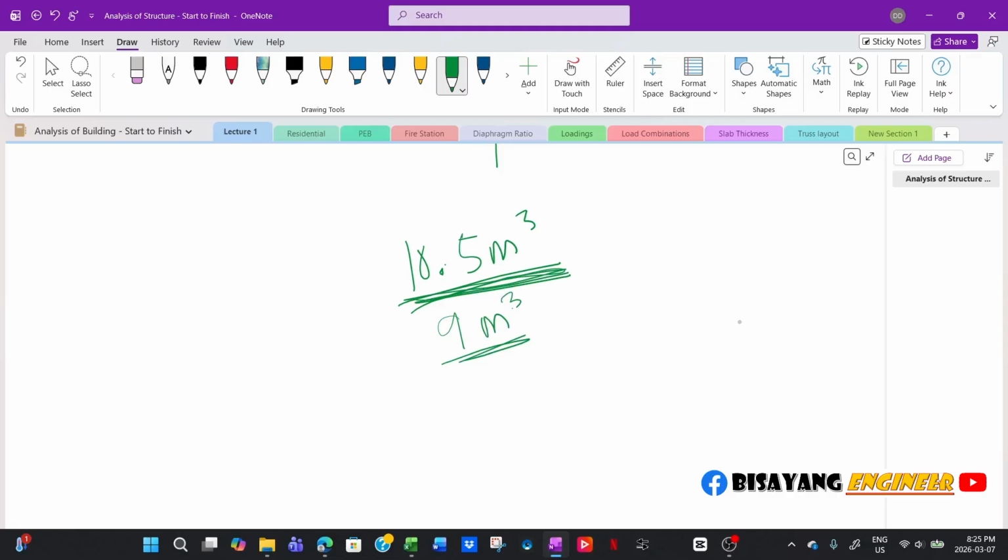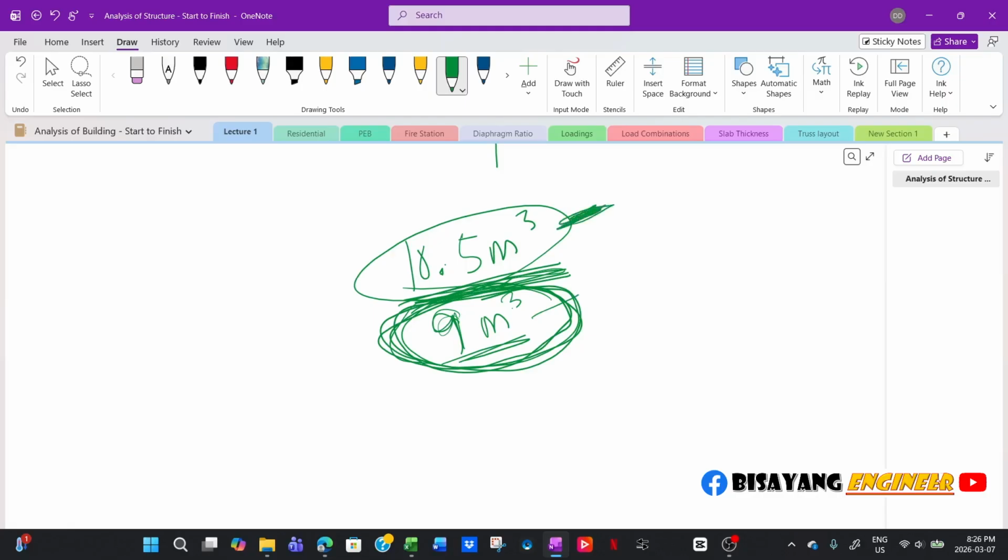Therefore, at maximum precipitation, water will not come out of the scupper or your discharge, in hydraulics, that's spillway or something, whatever you call it, but in architectural, that opening is called a scupper. If the volume from the precipitation is less than the calculated volume of your roof itself, then you have the option to use either this one or the maximum, this one here.